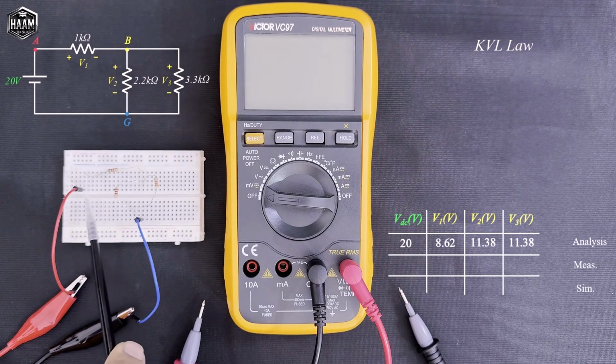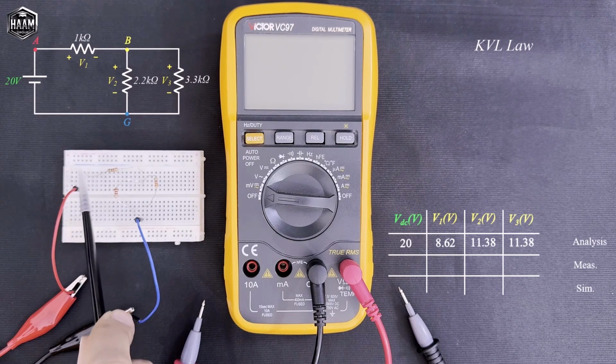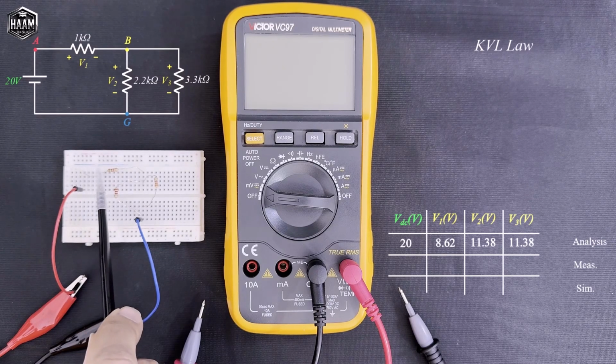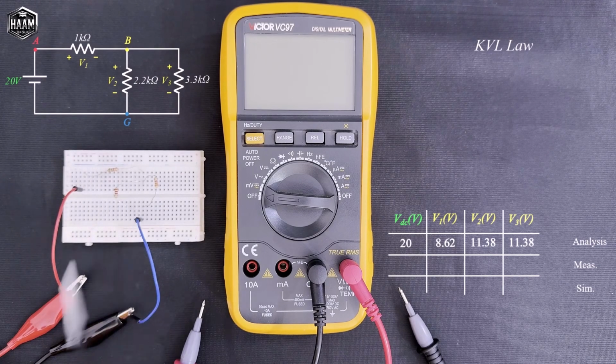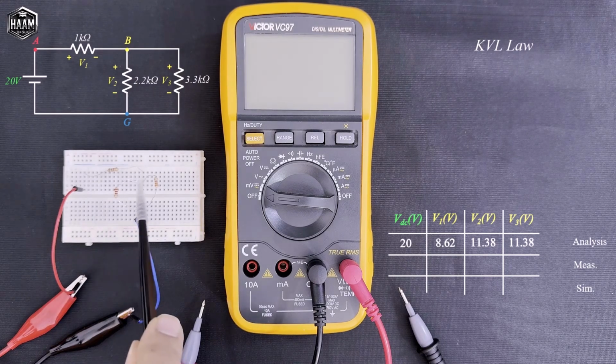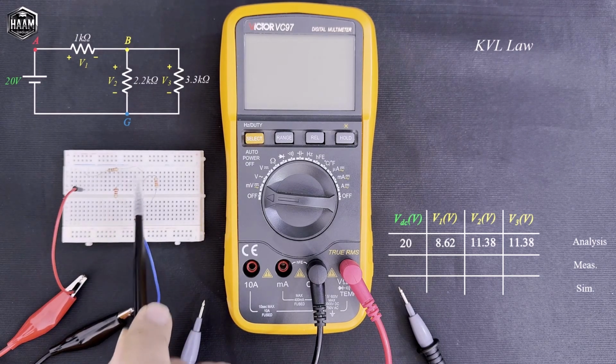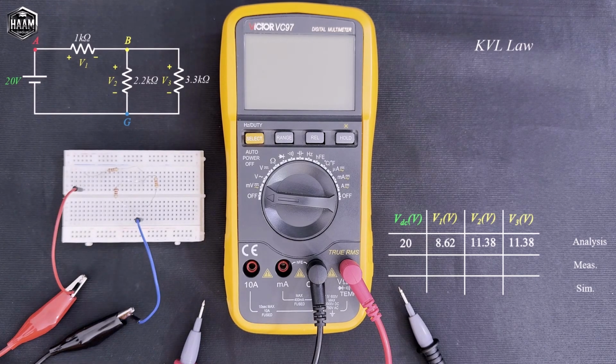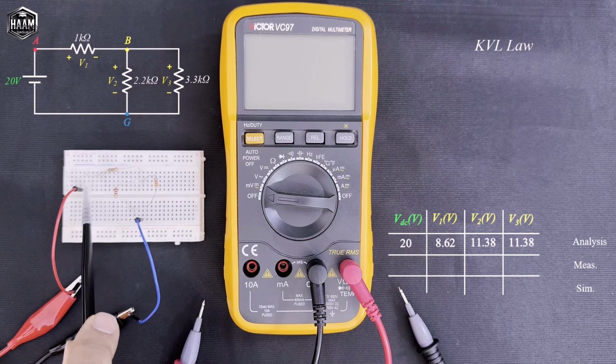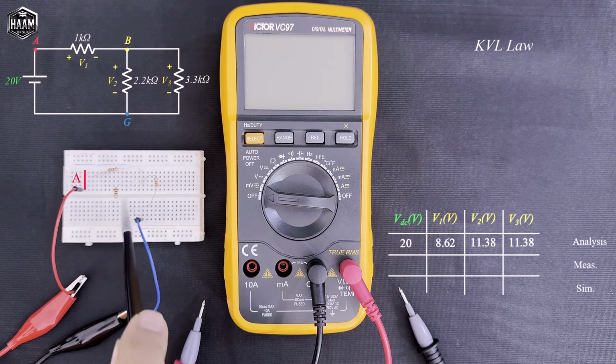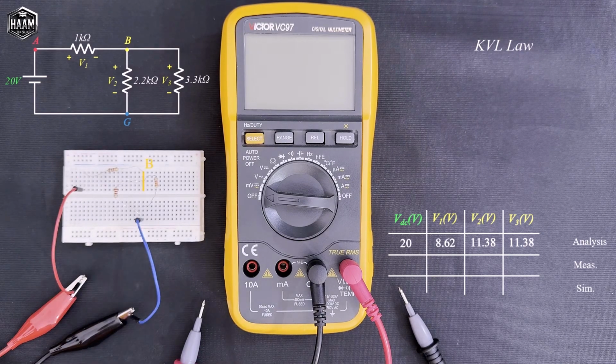Okay, the circuit is made up of a node A, where the positive terminal of the DC battery is located here. Resistor R1, which is 1 kilo ohm, is between node A and node B. Also, 2 resistors connected from node B to ground or node G. So here, this column is node A, this column is node B, and this column is node G, or the negative terminal of the DC battery. The ground node is considered.